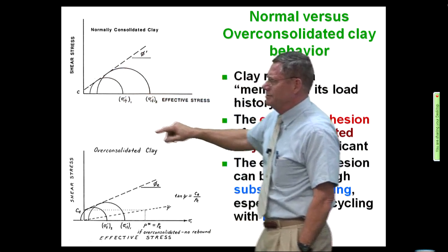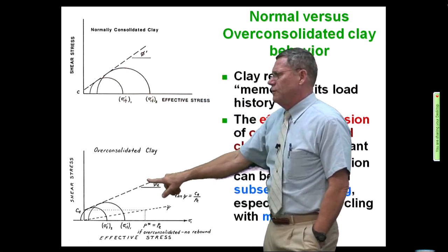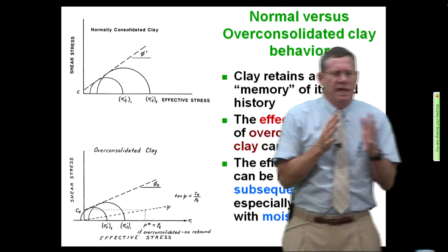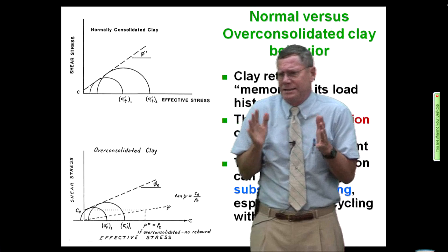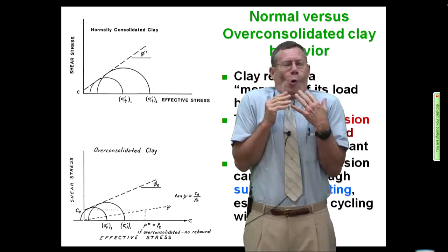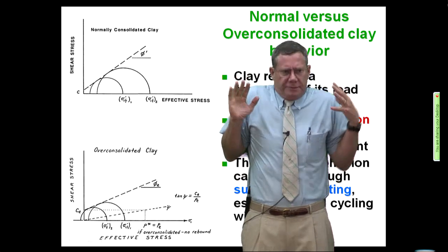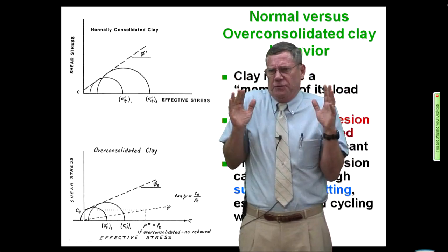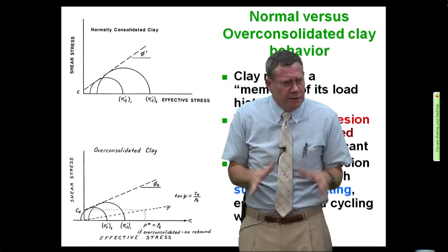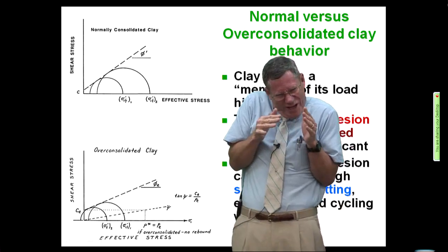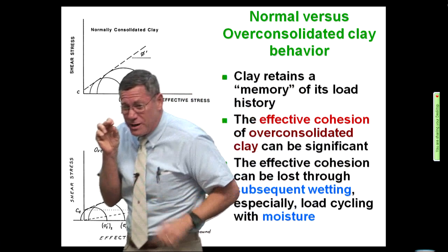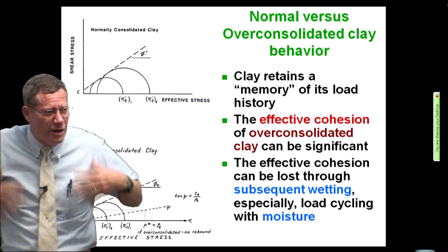It isn't that simple. And most of the time, you're dealing with overconsolidated clays. What does that mean? That's a clay that's dried out. And when it dries out, it'd be like my body dying and getting mummified. Is it going to change? It's going to have all these incredible suction forces as all the fluids drain out of me, and I'm going to pull tightly together, and I'm going to be a hell of a lot stronger per square inch than I was when I was filled with all this water.